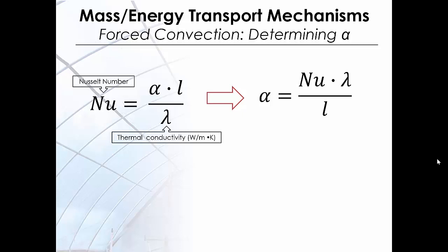In the Nusselt number, lambda indicates the thermal conductivity, and L represents the characteristic length or the characteristic dimension of the surface. Selection of the characteristic length should be in the direction of growth or thickness of the boundary layer. For instance, some examples of characteristic lengths are the outer diameter of a cylinder in external cross flow perpendicular to the cylinder axis, the length of a vertical plate undergoing natural convection, or the diameter of a sphere.